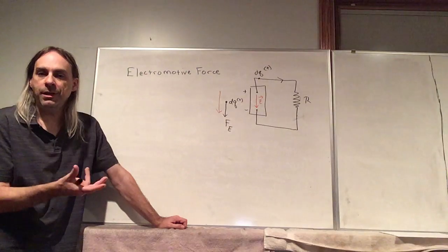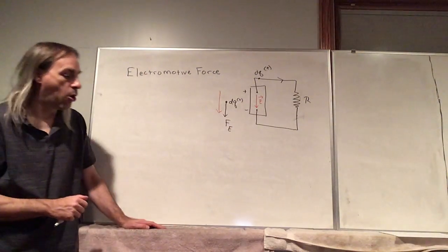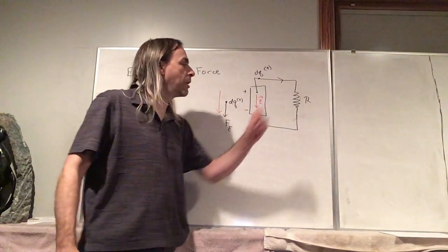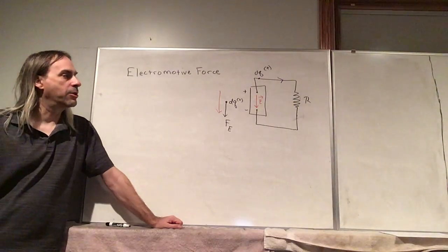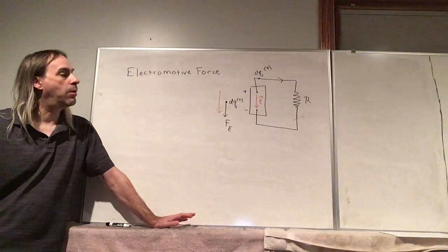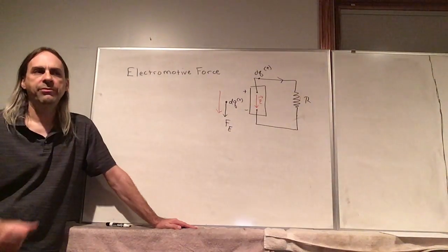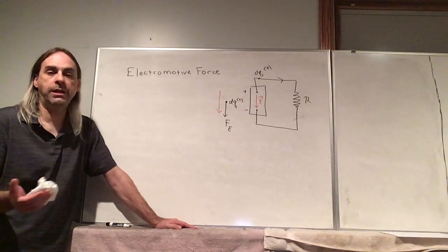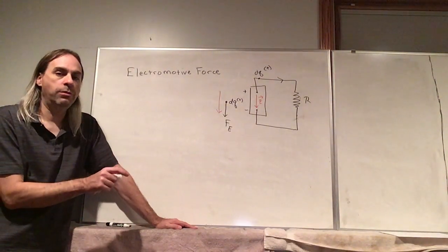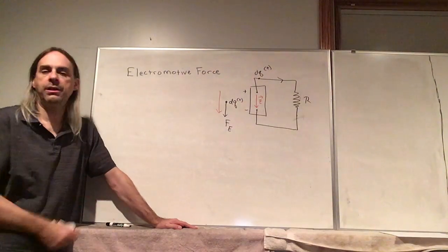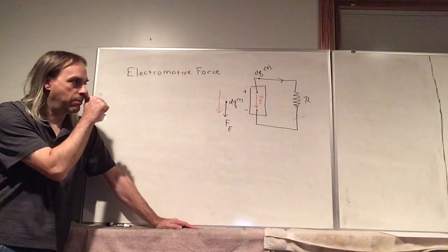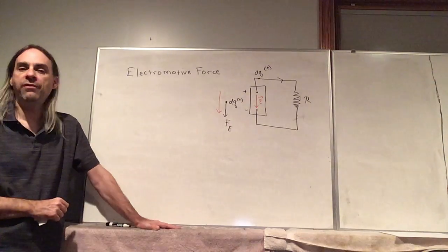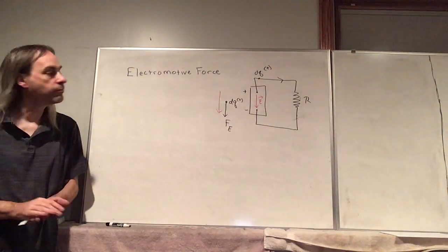Now, what about the wires? Again, insignificant. So we just ignore any kind of energy loss through the wires because, say this is a 100 ohm resistor, the resistance in the wires would be milliohms at best. So, completely insignificant. And another thing, if you buy a commercial resistor that's labeled 100 ohms, if you actually measure it, you're not going to read exactly 100 ohms. We typically don't have too much precision in these things anyways. So we're totally justified in ignoring the wires themselves.